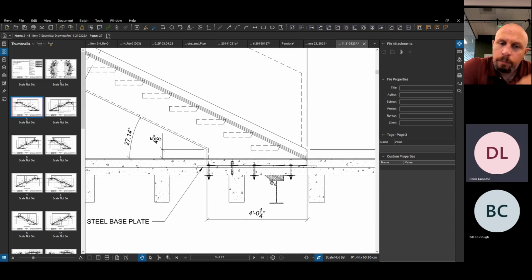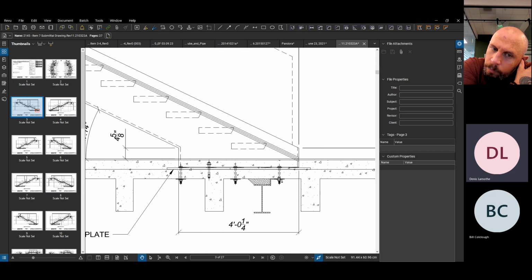And at the bottom, we did a base plate, but we were able to through bolt to the underside of the floor slab and have access to the anchor rods, and just put in a plate washer and a nut, tighten it up.